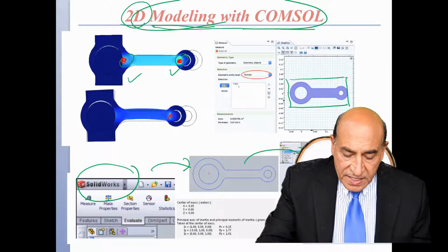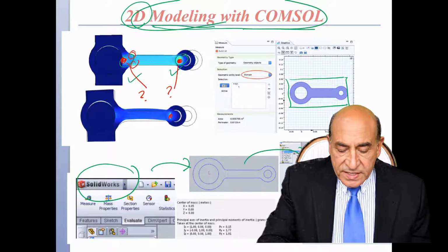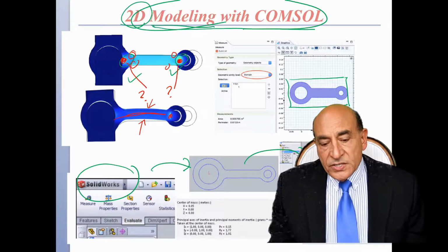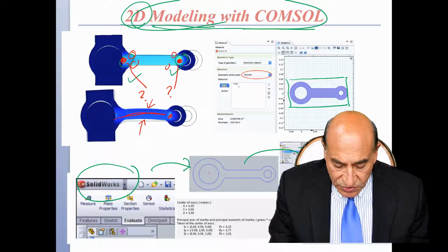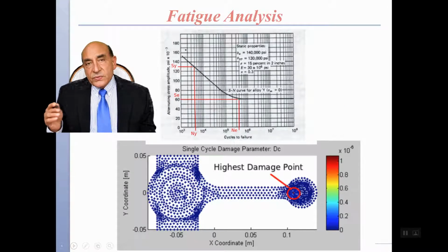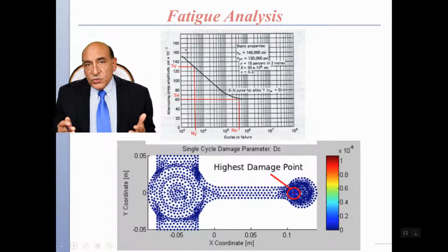So the question is, is this stress too high for failure, or do we have other stresses at specific corners? And what kind of deflections do we have in the rod? Is the deflection too excessive? That kind of analysis leads us to the next step in our quest for optimization, and that is to use failure theory that we will learn in the course to assess whether the connecting rod meets design criteria, or to determine whether it is actually optimal.